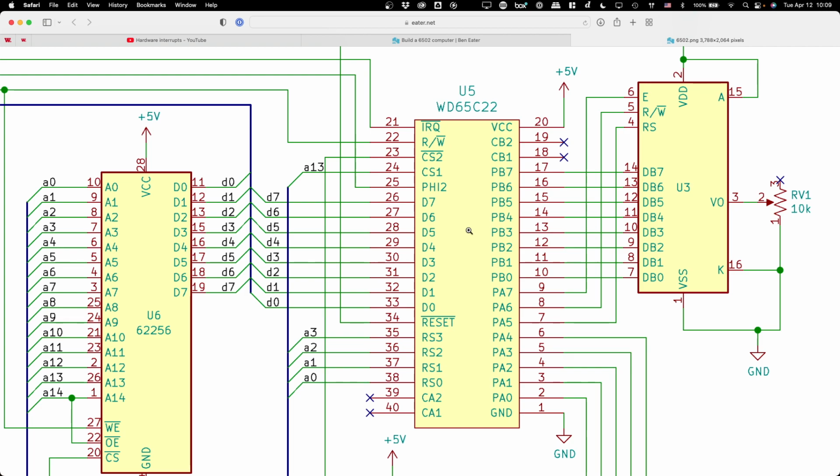After many hours on both Reddit and digging through the manuals, I'm pretty sure I've figured out exactly how this works. Basically, under what conditions does the 6522 trigger an interrupt? On the 6522, there is a pin for interrupt request, and this means that chip can bring the interrupt line low.